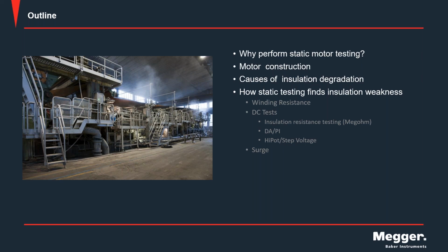So the tests that we'll highlight today will be the winding resistance tests, the DC tests, which include insulation resistance testing, the MEGGER test, the DA, the PI, high pot or step voltage testing, and then finally we'll end with surge testing.